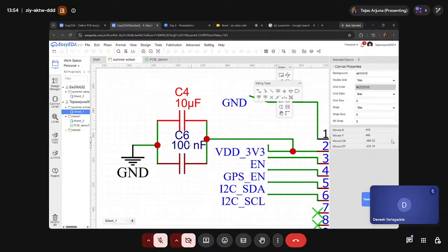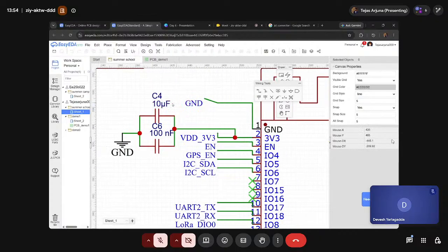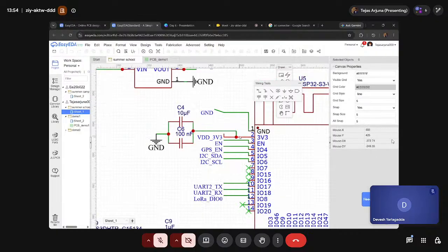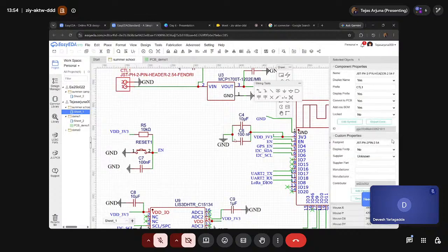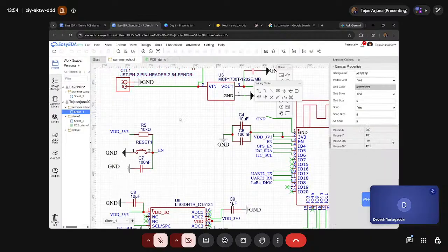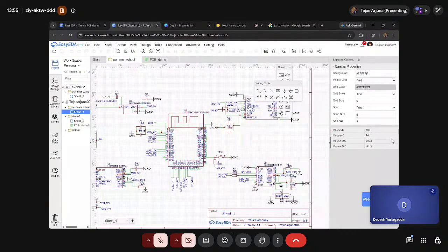what this does is, a larger capacitor can store a larger amount of charge, and when there is a current spike in this VDD, it can provide the current directly and is not required to get it from the external supply. The external supply is a long way away, and that's also a problem. That is the reason we are using a decoupling capacitor.